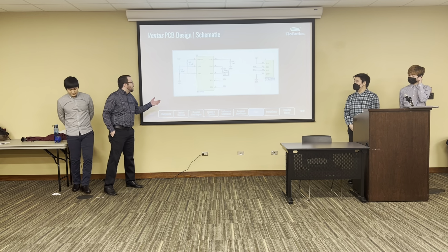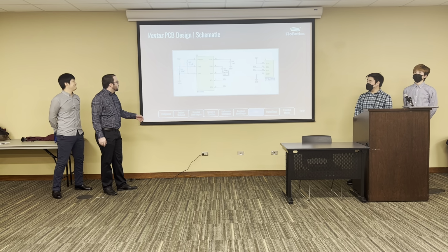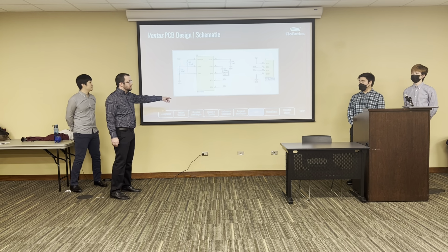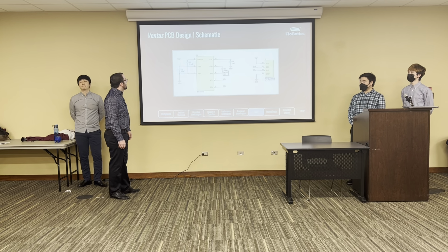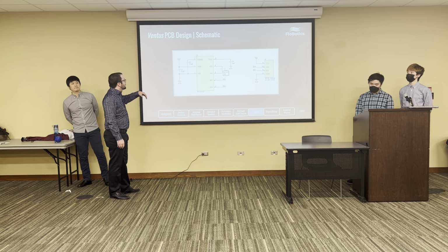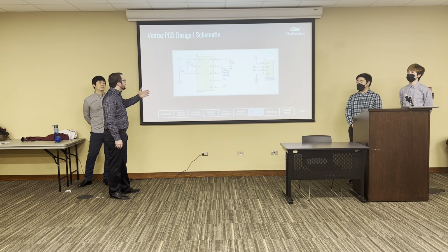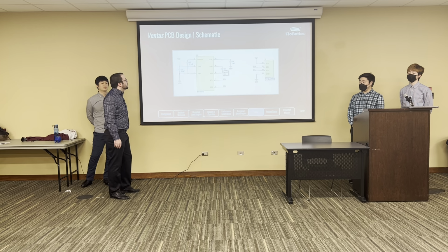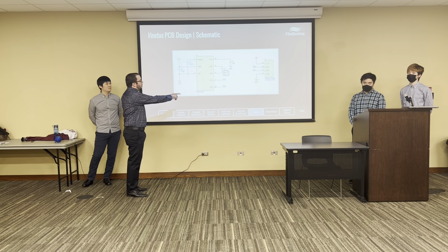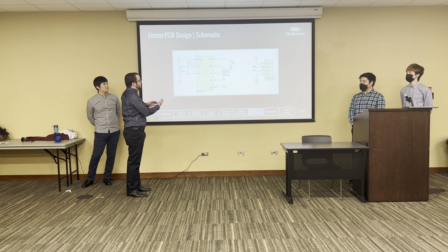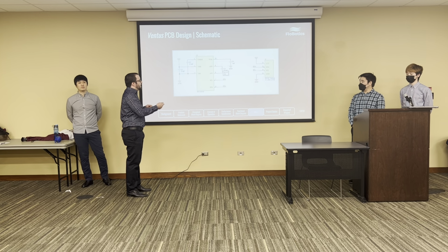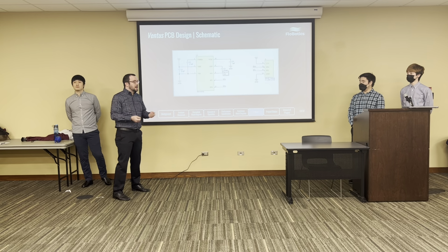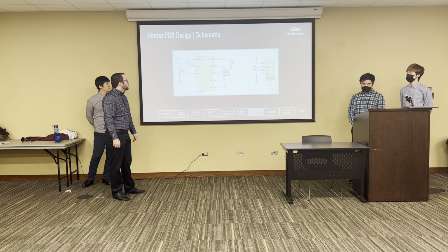All right, this is our schematic that was done in Altium. On the left, you can see our PAV 3005D. The capacitor values, we were suggested to use those by Posifa, which is the manufacturer of the airflow sensor. And on the right, you can see our quick connector, which actually goes on the back of the PCB, which allows us to easily unplug and replug to interface with other I2C devices. In our case, we're going to be interfacing with a MUX chip.